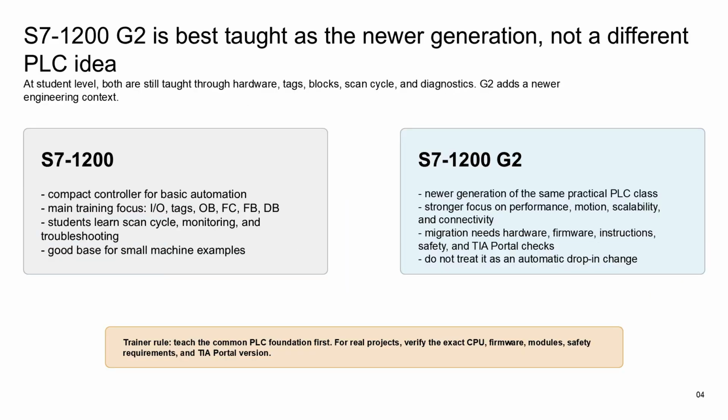Now see this slide. Main point is S7-1200 G2 is best taught as the newer generation, not a different PLC idea. Remember, at student level, both are still taught through hardware, tags, blocks, scan cycle, and diagnostics. G2 adds a newer engineering context.